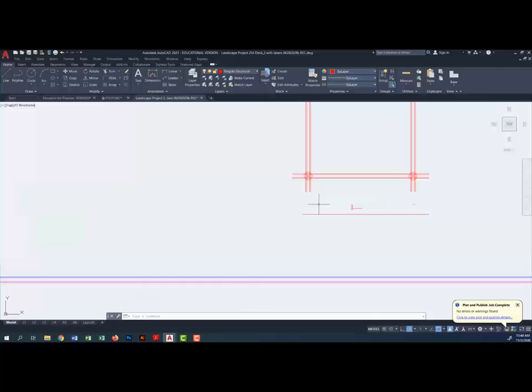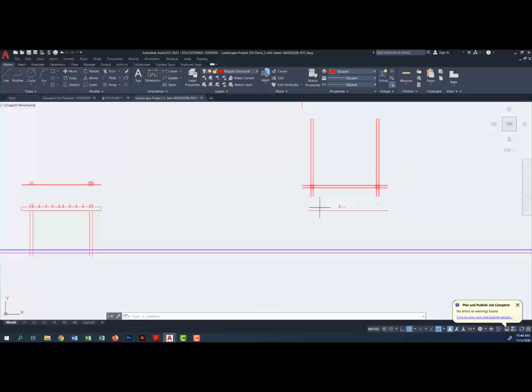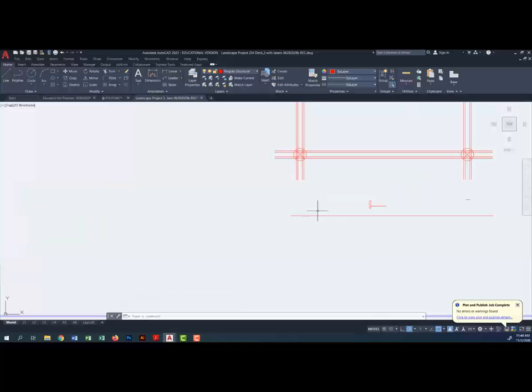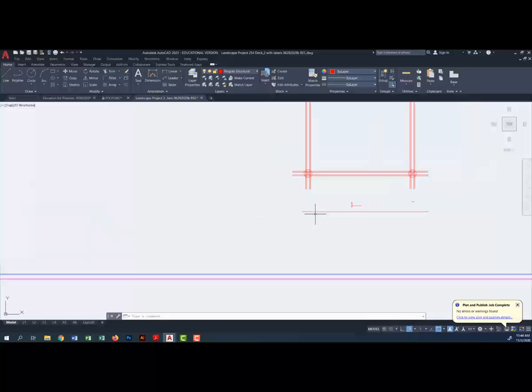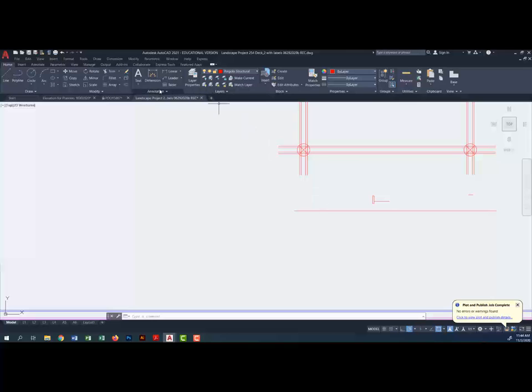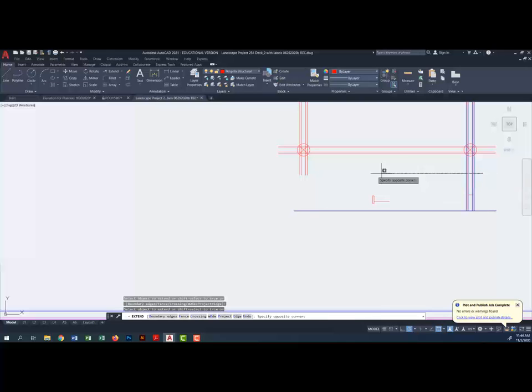So what I have in here is now I'm looking at the lintel straight on. That's the lower line. That's the flat view of it. Now I'm looking at the vertical view of it. So I'm going to extend to here. These are my lintels. Okay. What heights are they? Well, as I mentioned to you earlier, these things are 9¼ inches. So offset 9.25.